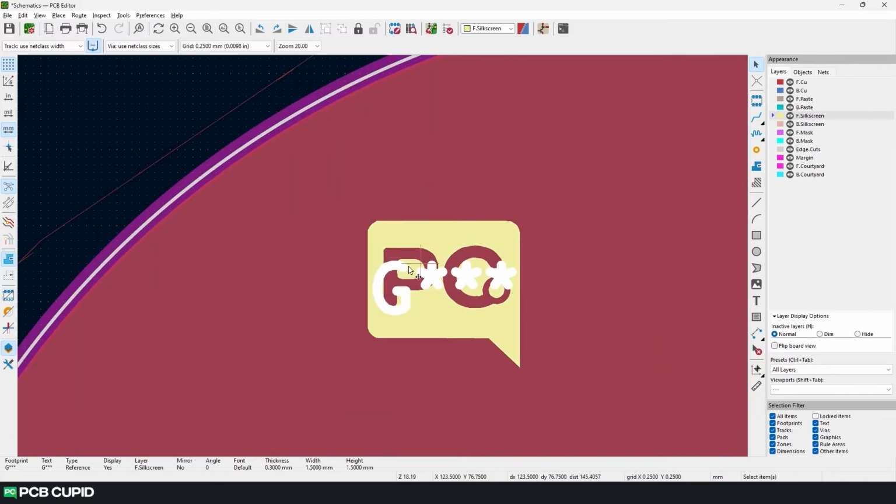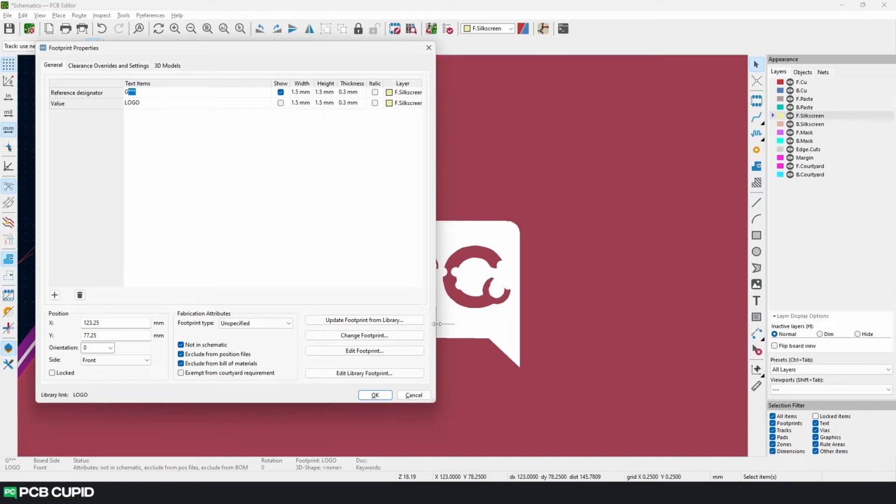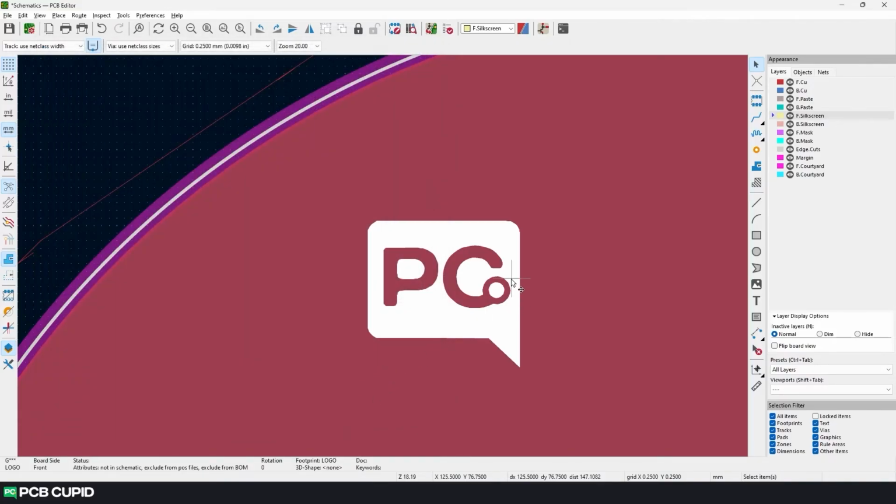Now you can see there is excess text along with the logo. We can easily get rid of this. Just select the logo and click the letter E. Now under the reference designator, uncheck the show option. Then hit OK.